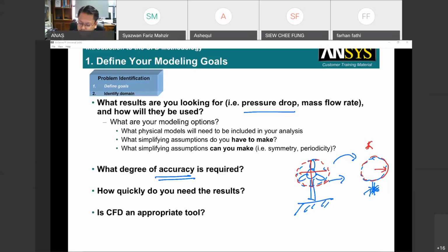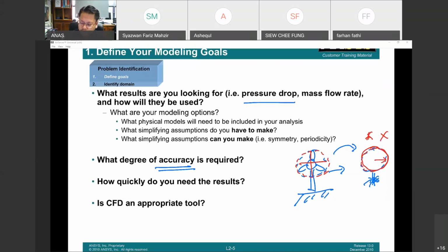Because by using this method, you just assume the turbine to be one simple circular disc. So you might want to use a more detailed method, which utilizes the details of the blade. So it depends on what you are trying to look at.